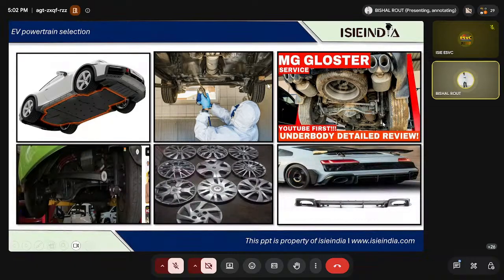Even the aerodynamic drag will depend upon the wheels, which you can see are consisting of something called a cover. These are called aero covers, basically, right? So if we place these aero covers, what is happening? The wheels are the largest contributor of aerodynamic drag force. Why? Because when wheels rotate, they accumulate all the air inside them. They won't release the air very easily, and that is the reason they are the largest contributor of aerodynamic drag force. And that is why your wheels need to be covered with a cover.